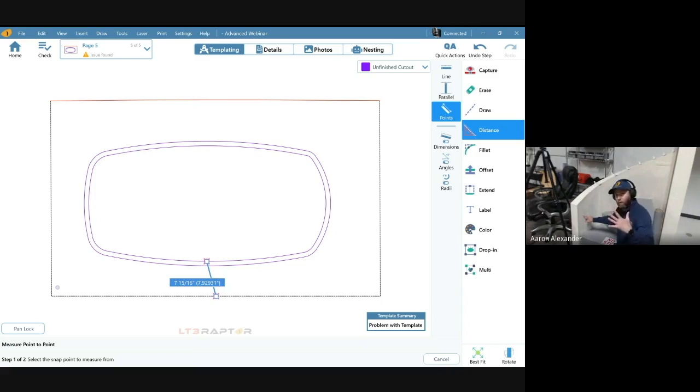Now, as you've seen over there, we just measured another 2 to create the next arc. It uses the third point as the beginning of the next one. So we do 1, 2, 3. Then we do 4, 5. There's another arc. 6, 7. There's another arc. 8, 9. Another one. 10, 11. Another one. Basically, when you're scribing drywall in arc mode, you just got to make sure when you stop, you're on an odd number. It's going to look for an odd number to complete the last arc. You can't stop on 20, but you can stop on 19 or 21, right?